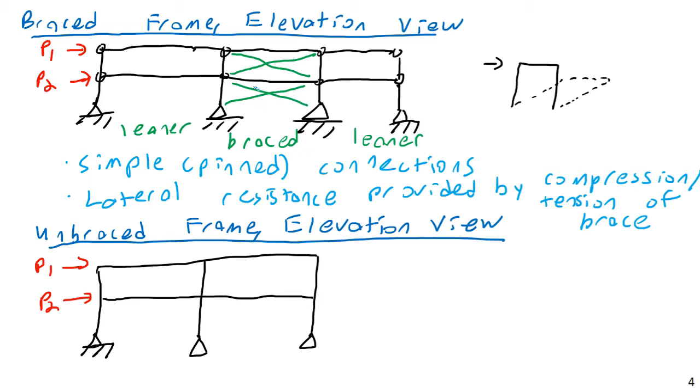Imagine you have your hallway, and a series of frames, and you're trying to make a hallway go through here. It's going to be very difficult to have an X-brace like this if you're trying to send a hallway through there. It's very difficult architecturally. So the downside of braces is that they require space. Yes, they're very efficient and they allow for very simple connections, but they take up a lot of space in a building. Or if you have one of these on one of the exterior frames, somewhere along a window, now you have a great big brace along your window blocking the view.